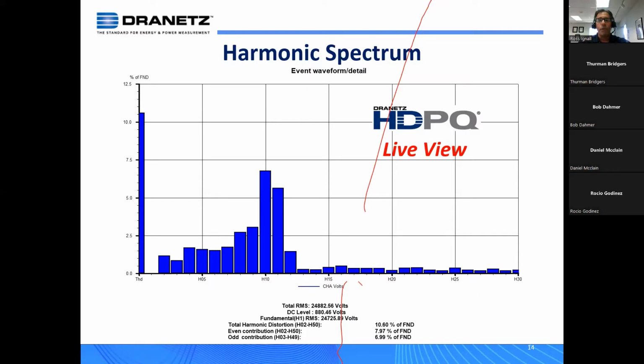So you have the ability to look at them both in units, volts or amps, or the ability to look at them in percentage of fundamental, more of a traditional way to do it. What you don't see here is the first harmonic plotted. In a theoretical system, 100% of your frequency component should be the fundamental. That's not realistic, but if we did display that fundamental here, it would rescale the screen. You'd have this real big line, and you're looking for these smaller lines. So traditionally, we don't display the fundamental.